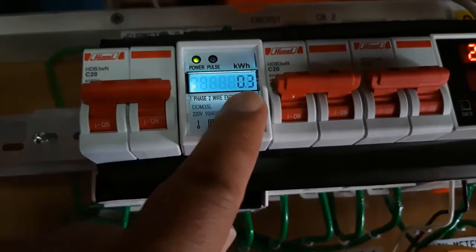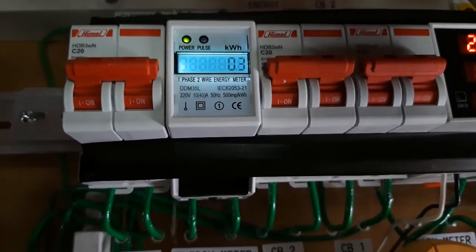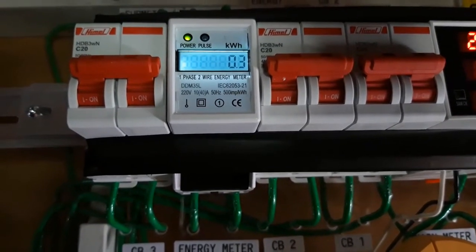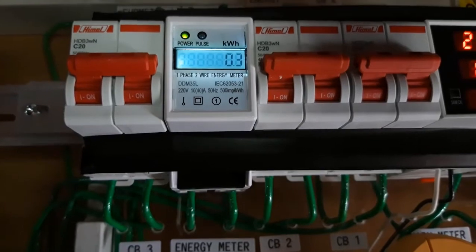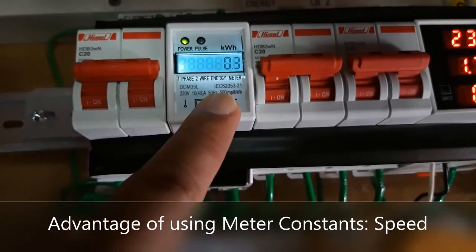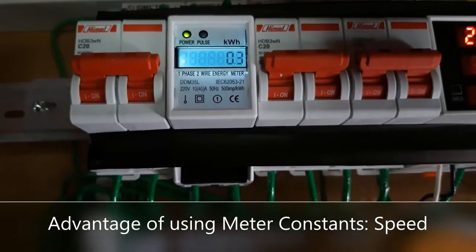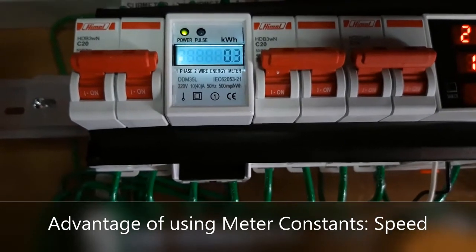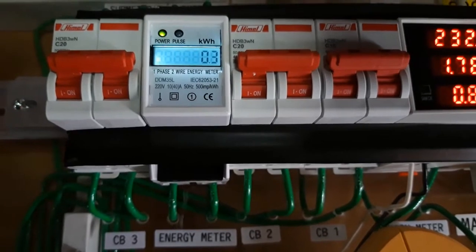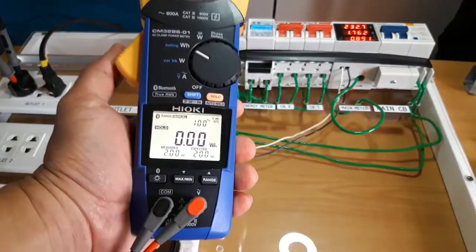The 0.3 digit there is not 0.3 watt hour, but 0.3 kilowatt hour. So that's a very large value compared to the 2 watt hour that we're measuring. That is why using the meter constant of 500 impressions per kilowatt hour would result in a much faster and also accurate result, for as long as we time our start and stop of measurement as perfectly as we can.